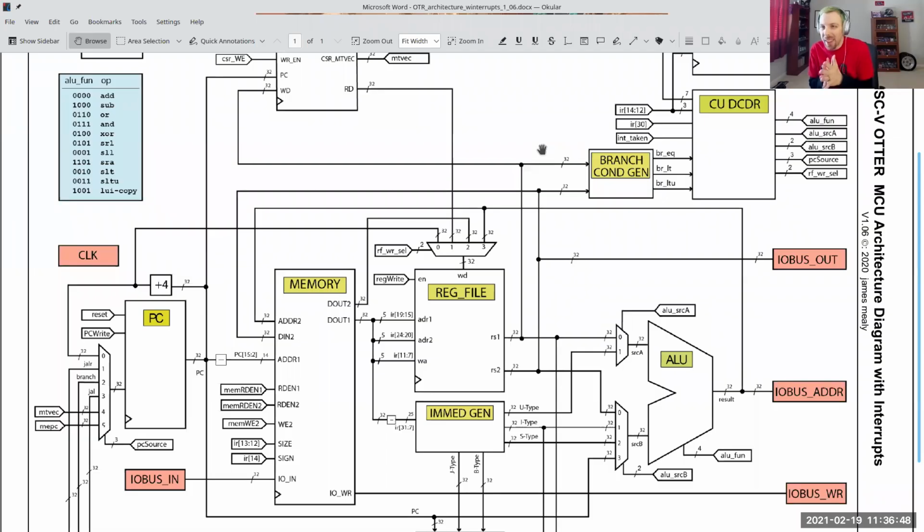And so if we think about what needs to happen in one clock cycle, let's think about this. At the beginning of the execute cycle, we get a rising edge. Rising edge puts out a brand new machine code. That machine code comes out and has to go to the reg file. The reg file has to then output the data on those regs, or it has to go through the immediate generator and output the data on that.